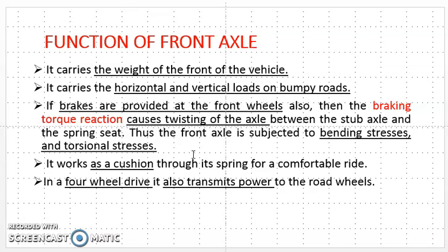Apart from the braking torque or forces, the front axle should also provide cushioning through its spring for a comfortable ride, as well as, if the vehicle is four-wheel drive, at that time this front axle should transmit the power to the road wheels. Okay, all these are the function or requirement of the front axle.